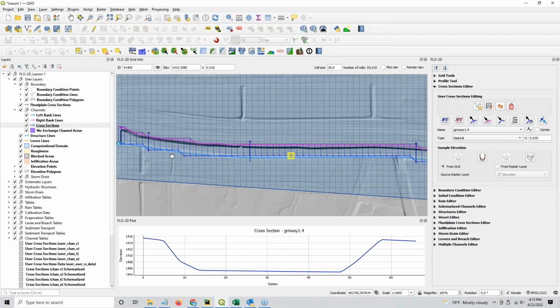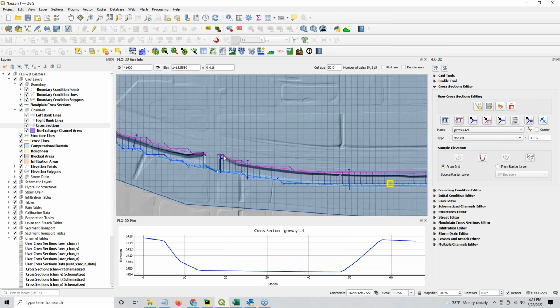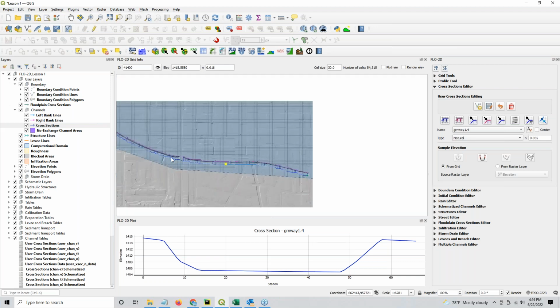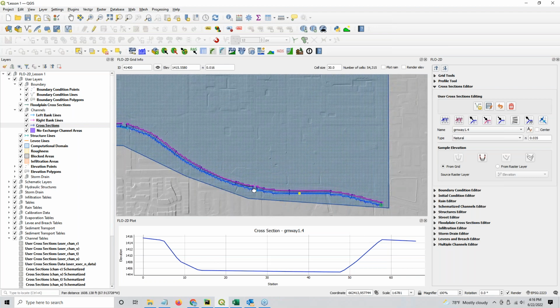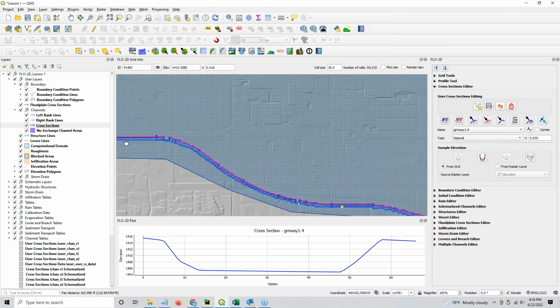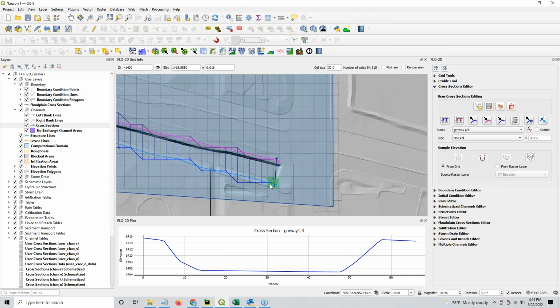If you're having problems with a hydraulic structure, the biggest issue with hydraulic structures is that you don't develop this transition into your geometry, into your cross-section geometry. That's the number one problem with them. Another problem with channels is, so I'll increase the n value leading up to this, increase the n value coming away from it. Just slight increases in n value can resolve a lot of stability issues. If you're having problems with all your problems are kind of related to your inflow node, just bump this cross section up a little bit so the water flows away from this inlet node or inflow node.